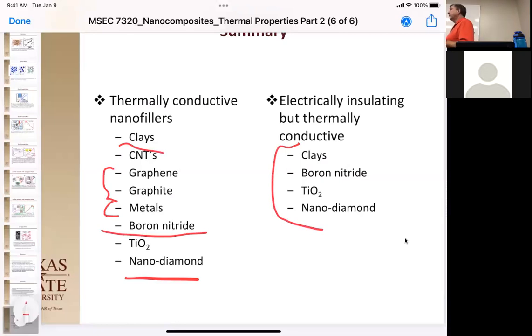I want to make sure that you looked at those. All those carbon ones are electrically conductive. Now they're also low density, so that's a good thing too. So when we're looking for these, we're looking at clays for our lower density side, and titanium oxide for our higher density side. This might be a really simplistic question, but the reason that the graphene and the CNTs are conductive, but the nanodiamond isn't, is because of the double bonds, right? Yes, conjugation. That is exactly right.